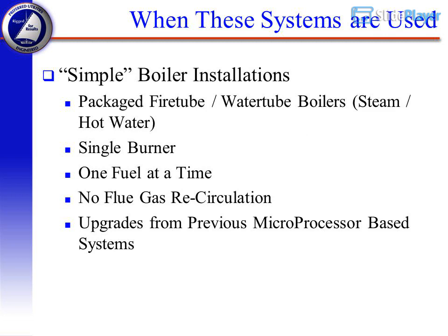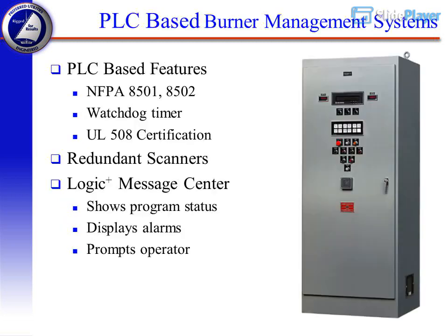Used for simple boiler installations: packaged fire tube and water tube boilers, steam or hot water. Single burner, one fuel at a time, no flue gas recirculation. Also used as upgrades from previous microprocessor-based systems and PLC-based burner management systems.